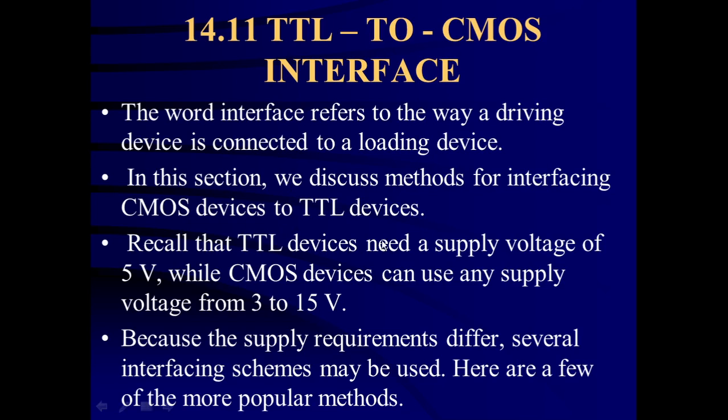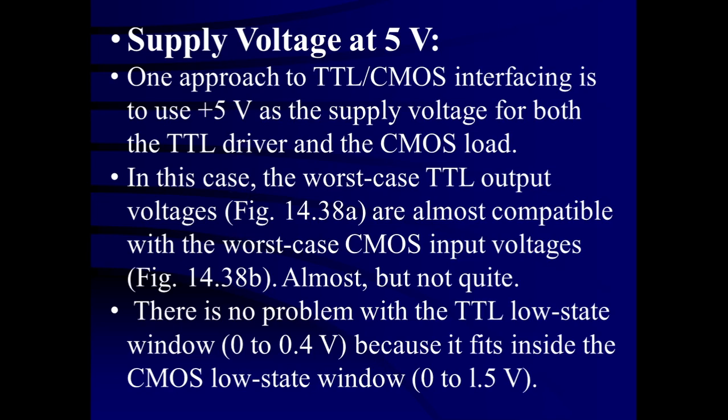Recall that TTL devices need a supply voltage of 5 volt while CMOS devices can use any supply voltage from 3 volt to 15 volt. Because the supply requirements differ, several interfacing schemes may be used. Here are a few of the more popular methods we are going to discuss. First, we study the TTL to CMOS interface. That means TTL will be working as a driver, so the output of the TTL is connected to the input of a CMOS device.